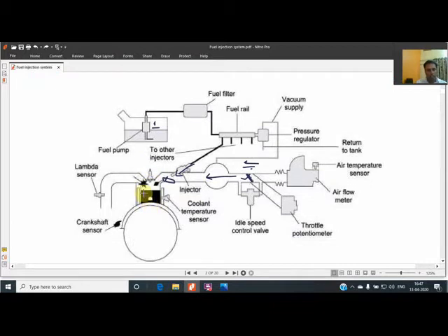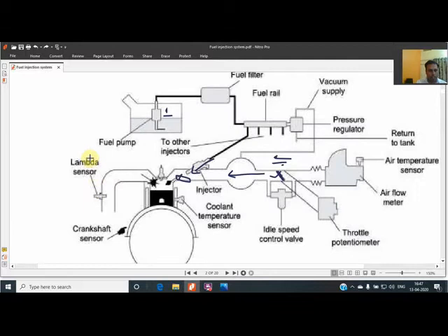And thereafter, when the complete cycle is completed, the burned gases go out, and in between they are sensed for how much oxygen is there in the burned gases, because we have to give the signal for the fuel metering, meaning how much fuel we have to give if the oxygen is less or more. For this they are using one oxygen sensor. The technical name they have used is lambda sensor. They have used it over here.